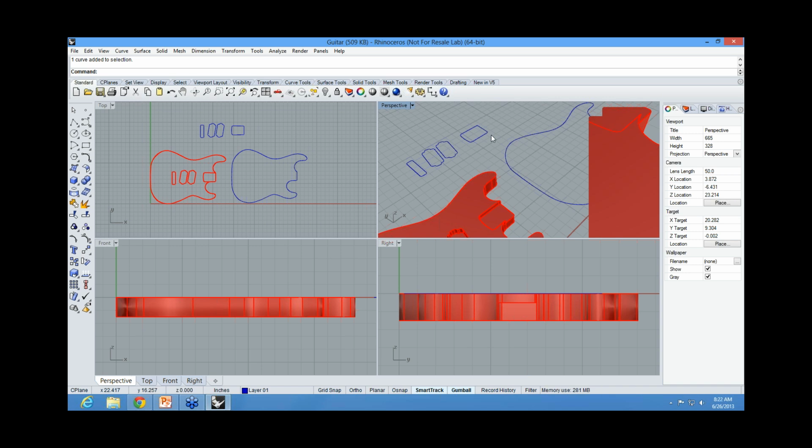Another area that I don't know how many people have run into, but we see it quite a bit in technical support, is the ability to use TrueType fonts in 3D modeling. TrueType fonts, when you're using fonts, are very, very poor geometrically. They have a lot of overlaps, they have a lot of small loops, and you'll find you'll have a lot of problems using them in trimming, creating solids, Booleans, all those types of things. TrueTypes can be terrible that way.